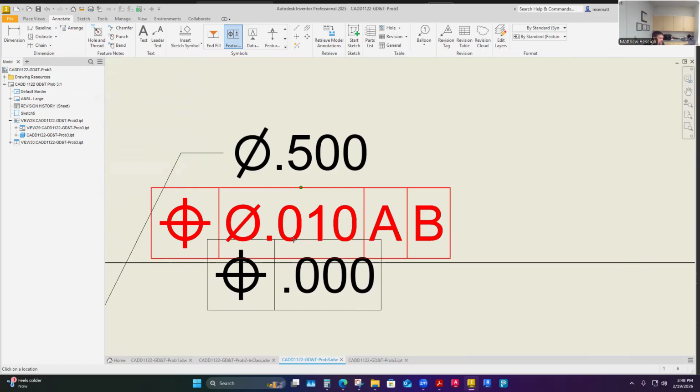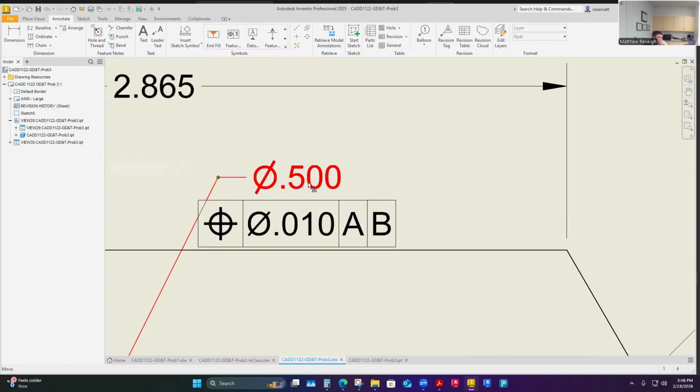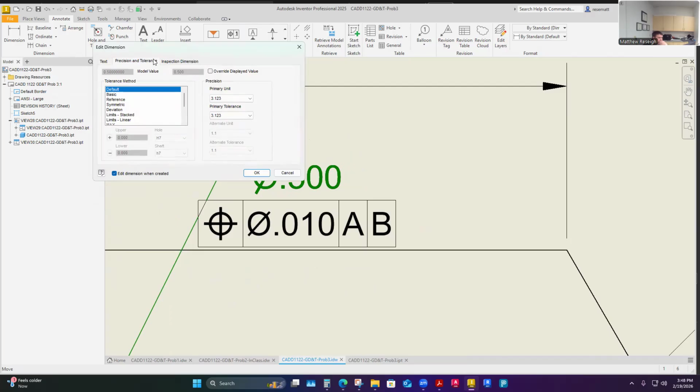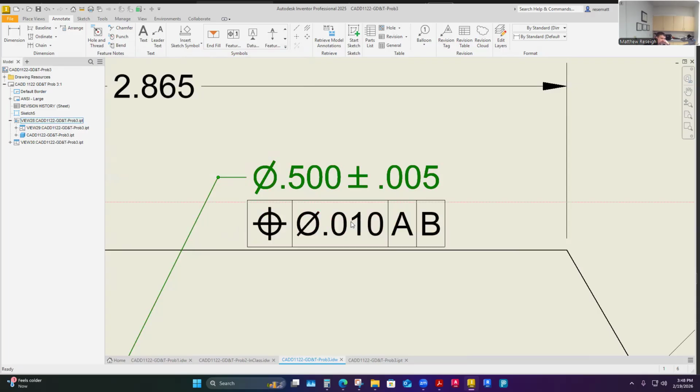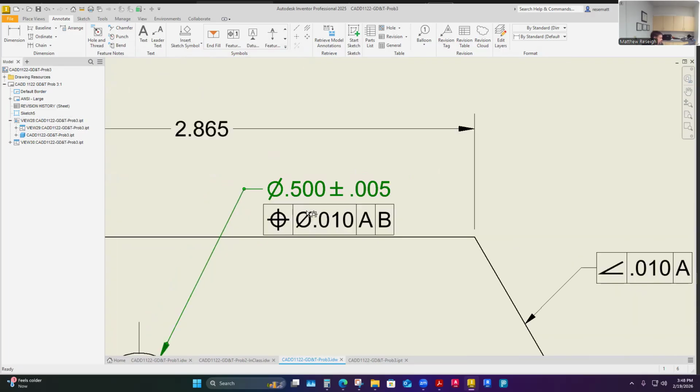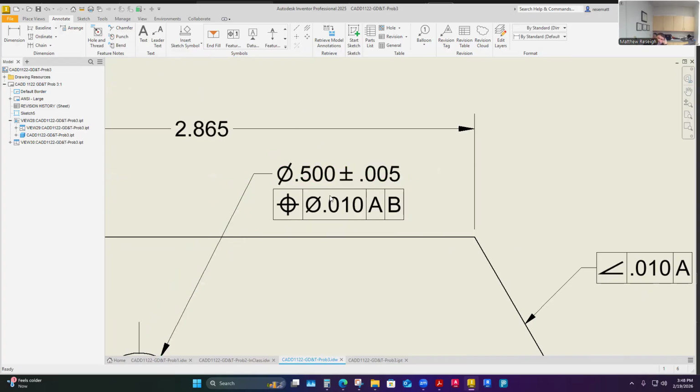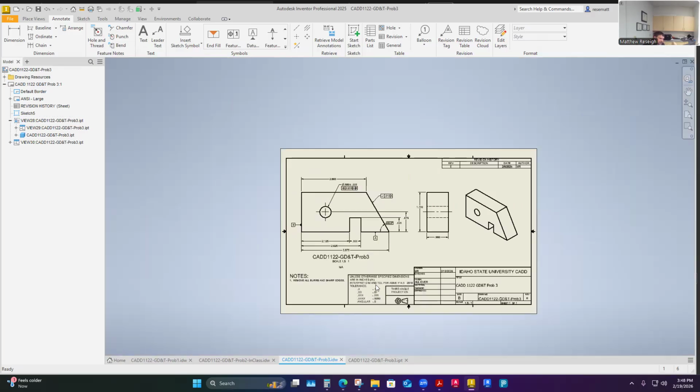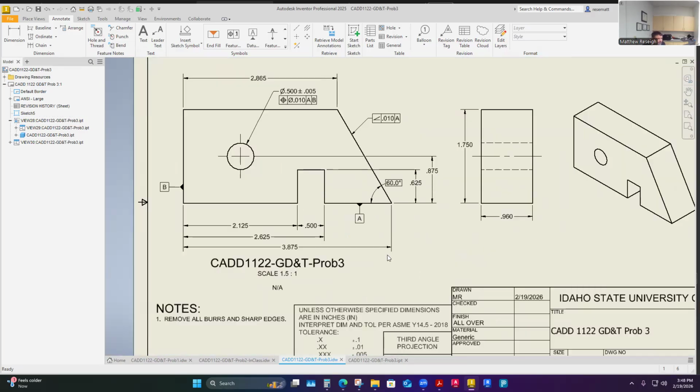I think I'm going to say okay. And I just said I was going to add the symmetrical tolerance to this, which is still three decimal places for that particular number, and it's going to be 0.005. So it looks more like this. This just helps me see what I've got to work with, and if I'm doing anything wrong there, it probably could be to omit that if it's being covered by this. So at least I'm aware of it. So there's my positional tolerance.